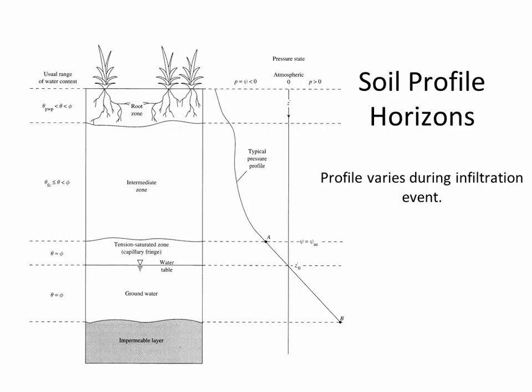All right, here is a soil profile. We need to get in the habit of looking at cross sections of the subsurface and being able to interpret what we're looking at. And so here's the rock layer at the very bottom. Impermeable layer means that there's rock, or in some cases a really impervious compacted clay, that we say the water table is perched on top of.